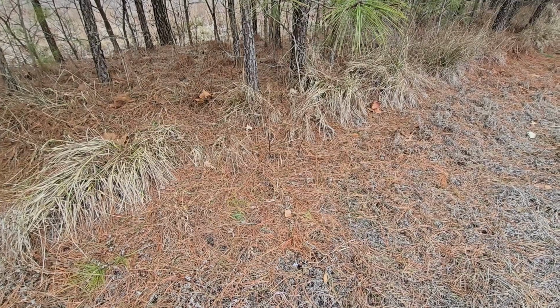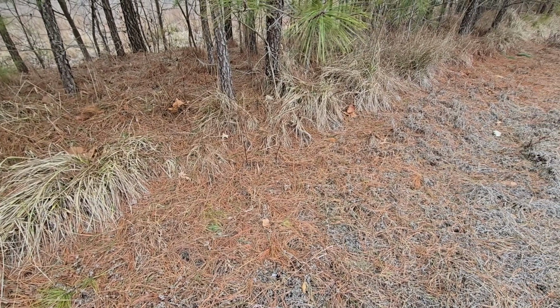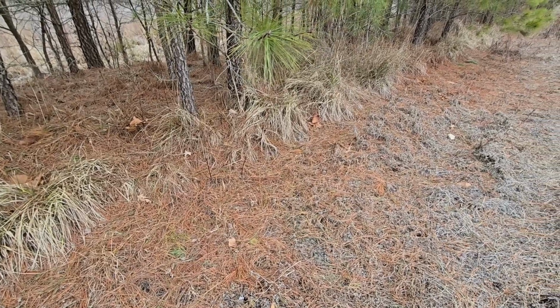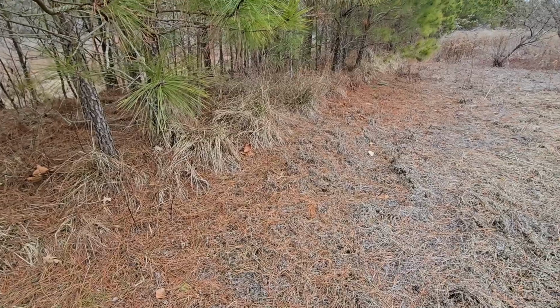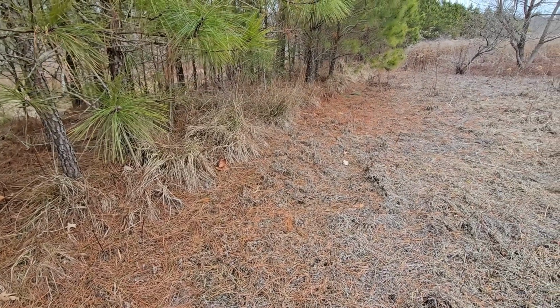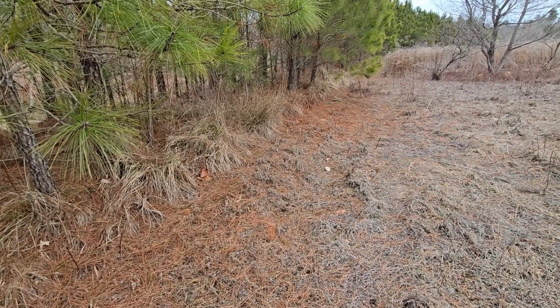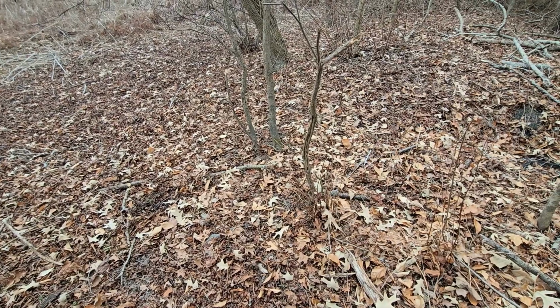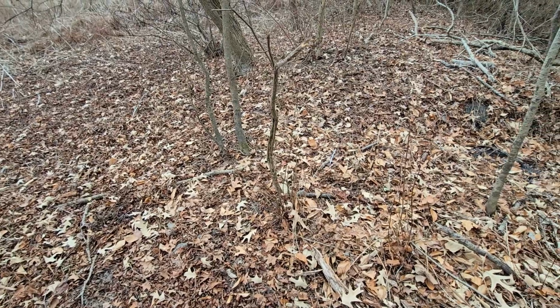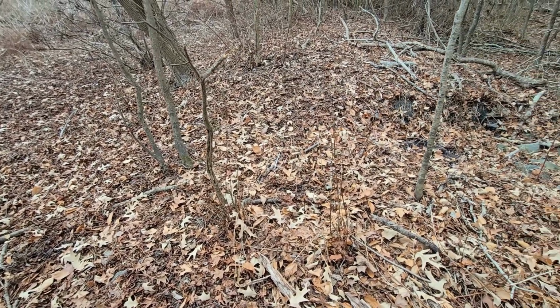You're looking at a dam that was built for a wetland mitigation project that was completed in Virginia. The dam is about 3 foot high and has steep side slopes. Pine trees are growing on the dam because it has not been mowed. The wetland that was created by building the dam is on the right side of the dam. The spillway for the wetland had been built in the center of the dam, not at one end of the dam like what is normally done.